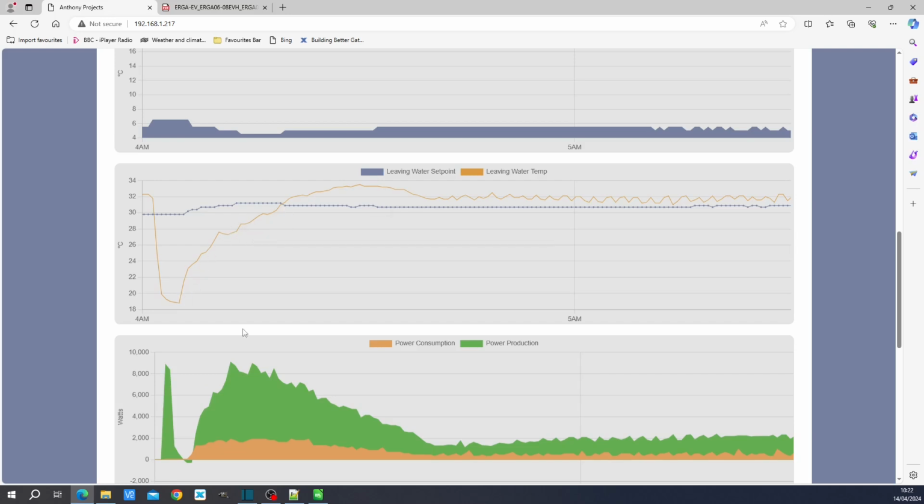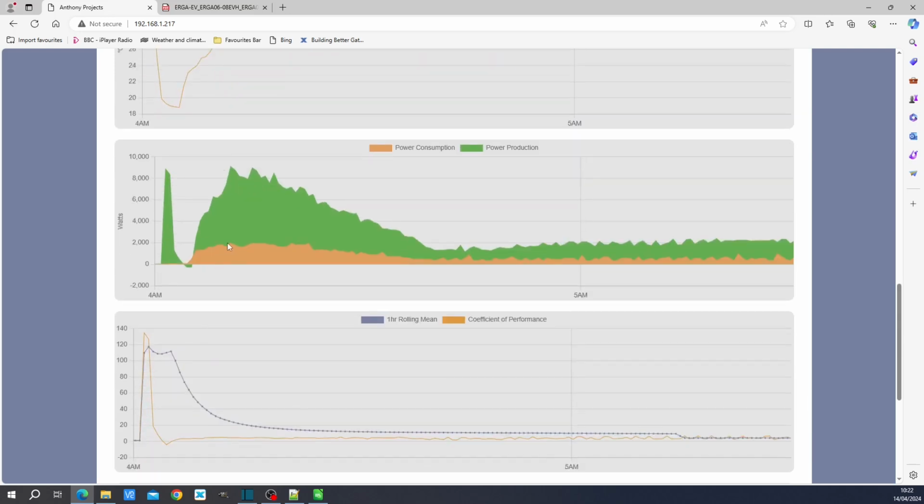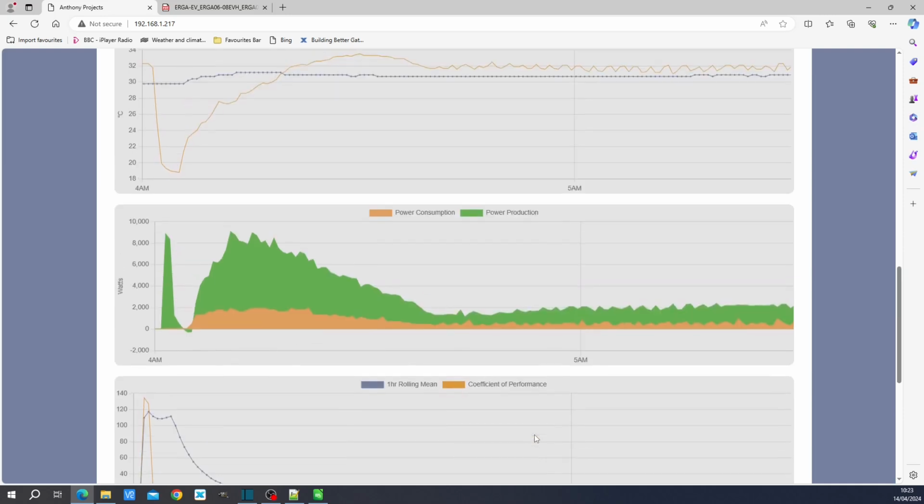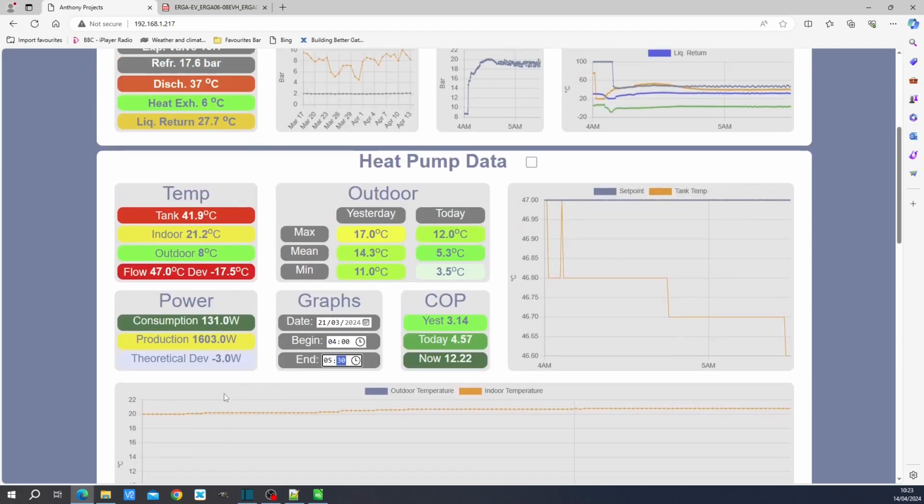So before the unstable regime, we've got quite a lot of output here, 2000 watts nearly, and that's delivering over 8000 watts of output. So we're getting a coefficient of performance which is over 4 in this environment here, and that continues all the way down here. So if you have a look here, coefficient of performance of 4.1. But once we get into this regime here, what are we getting? We're getting a coefficient of performance of 3.3, between 3 and 4. So again, let's see what's going on with the expansion valve.